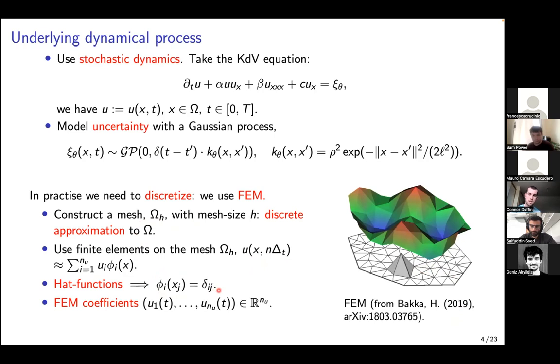The nice property is that they're compactly supported within a very small region about each of these intersection points. If you imagine on this mesh you've got a bunch of points upon which you're creating the mesh, then around a relatively small neighborhood, again governed by the mesh size H, these basis functions drop to 0. Perhaps intuitively, this is a basis function set that allows us to imbue some sparsity in the domain, because there's not so much overlap between regions upon which these basis functions are defined. So these are quite nice computationally because everything basically ends up being sparse.